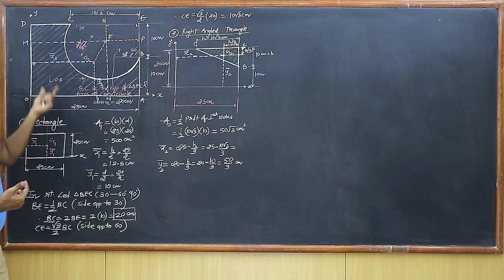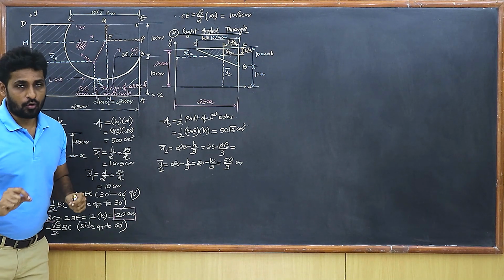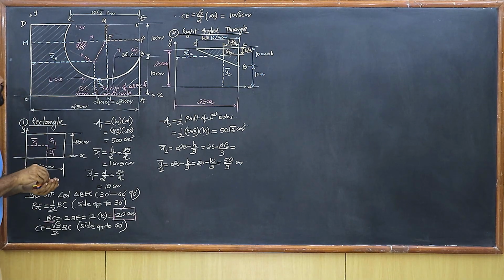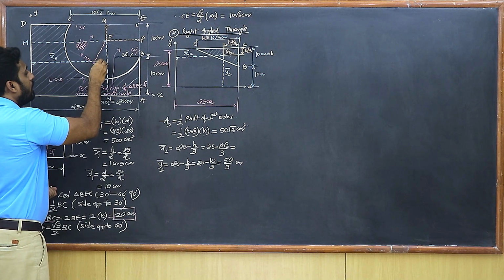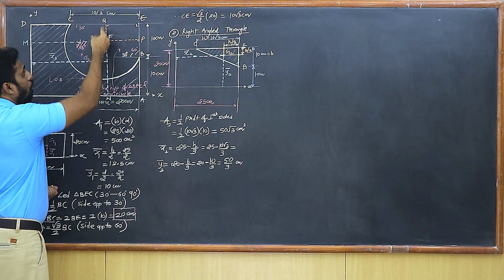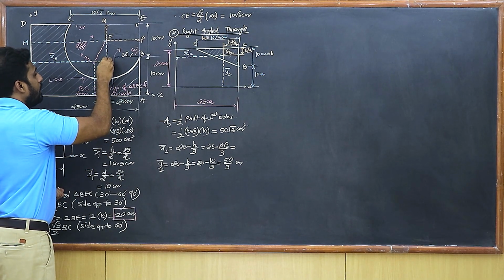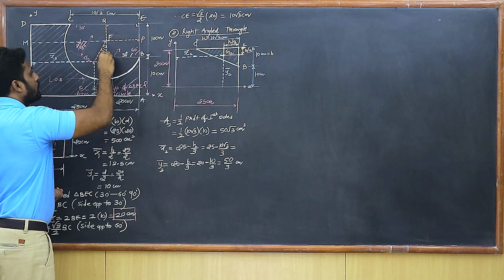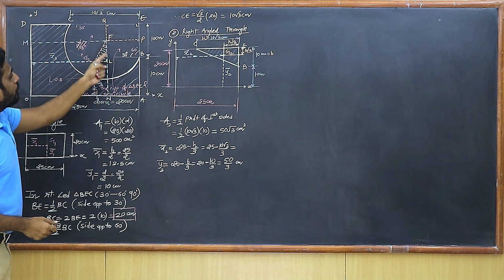My job is to get the value of x3 bar and y3 bar. Now the most important part of the solution. Look at this. From this G3, students, I'm going to draw another perpendicular on this FN, or QN you can say. Let us name this point as L, and you should focus on this small triangle FLG3.